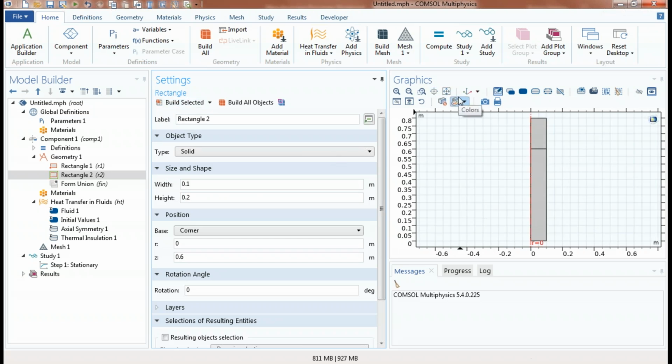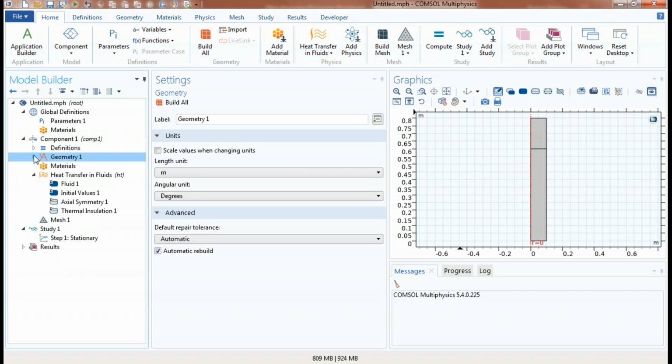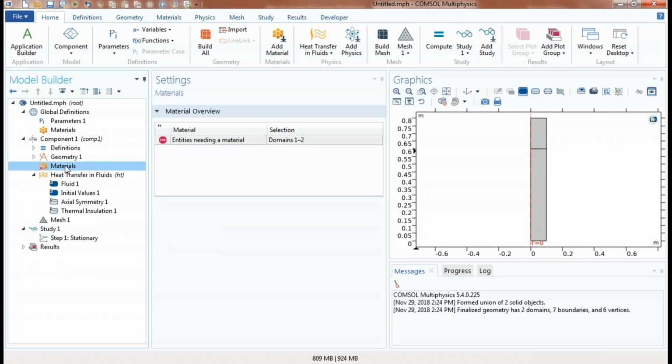So what I've created here is two sections. The first section is where the material will be contained within the mold. And then below this line will be the section where the material has come out of the bottom of the mold and is being cooled by some spraying fluid. So what I want to see is that the material has solidified, or sufficiently solidified, when it exits the mold. Okay, so I've got my geometry. I'm going to move on now to setting up the materials. I have to define two materials here, although in effect I'm only modeling one material.